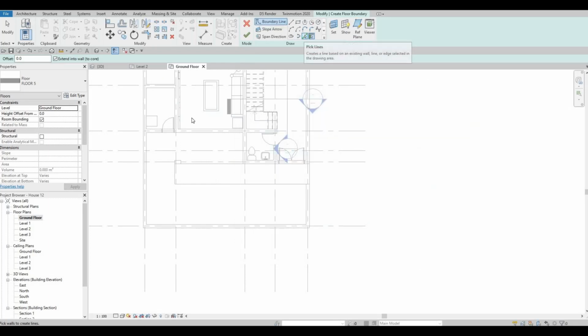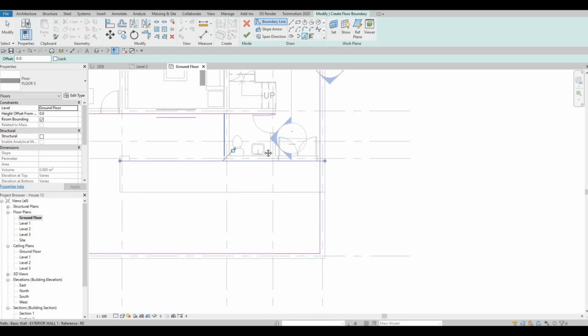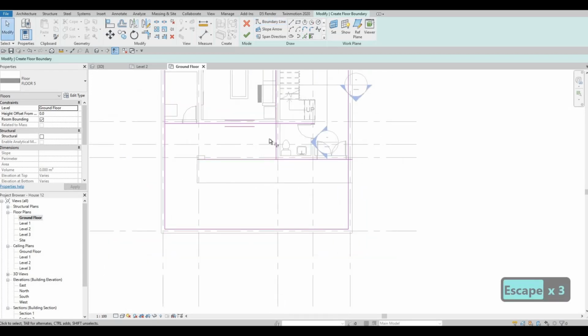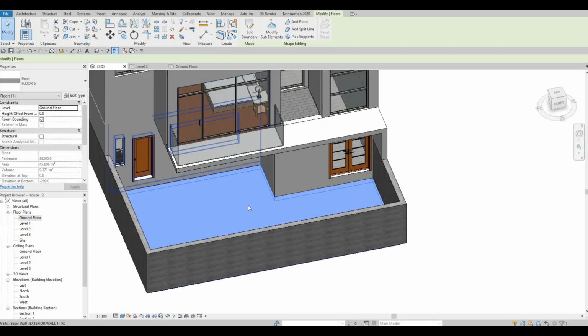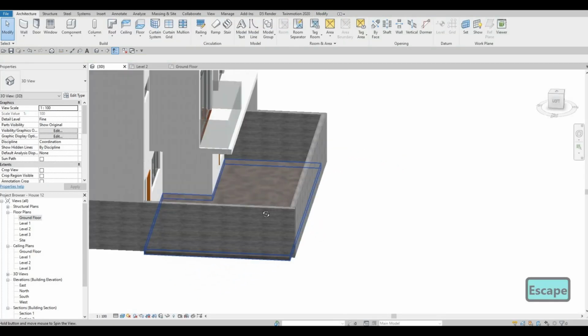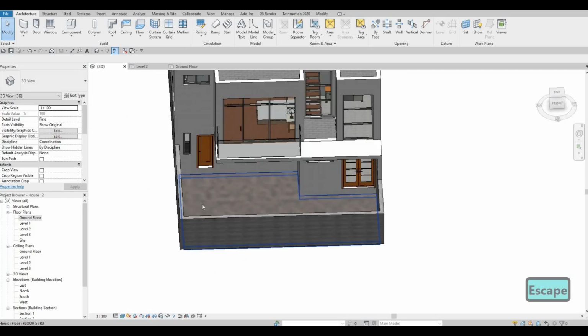And then here, using pick line, you need to pick the exterior walls, and then after that, TR, trim and extend. And then once you're done, click finish, and we want to double check. So I have it right there.